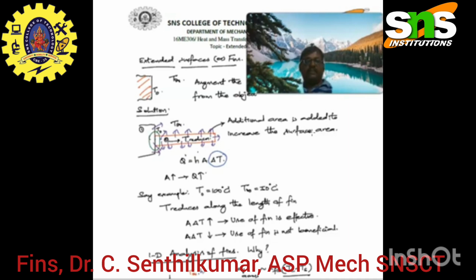We can see this extended surface in IC engines. You all would have seen the IC engine where the engine is covered with the extended surface, which is called fins. These fins are very good at increasing the cross section area based on the design parameter. Based on the design parameter, we can design thin fins or thick fins, rectangular or square, whatever shape and dimension we want, based on the nature of heat transfer.